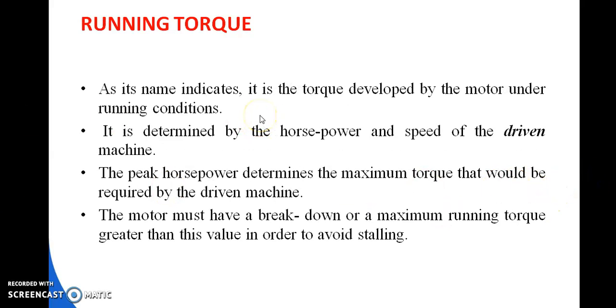Next, second one is your running torque. As its name indicates, it is the torque developed by the motor under running condition, that is under normal operating conditions. It is determined by the horsepower and speed of the driven machine.